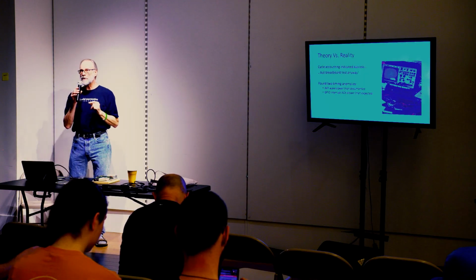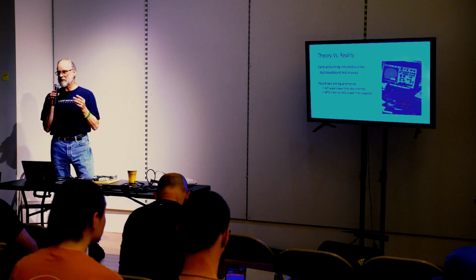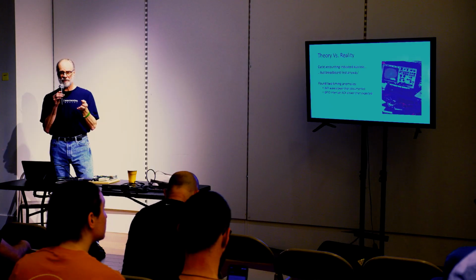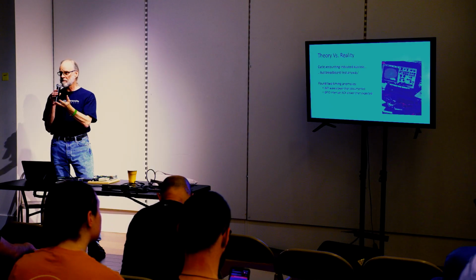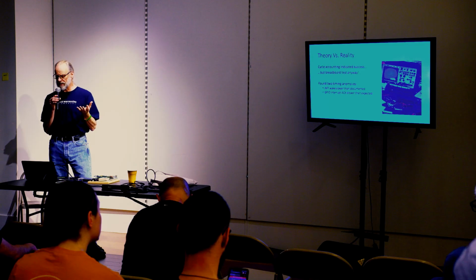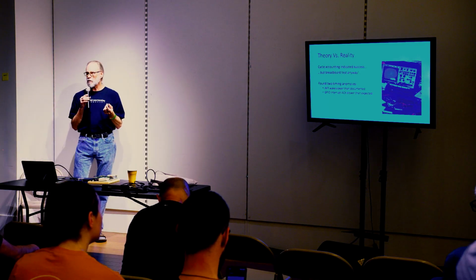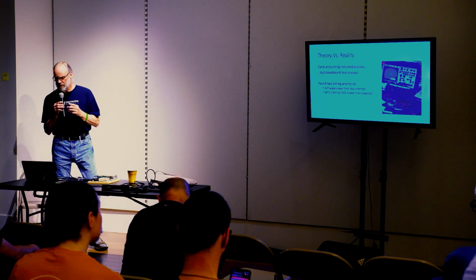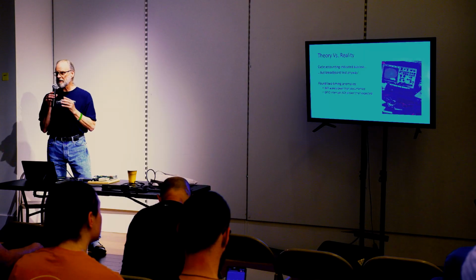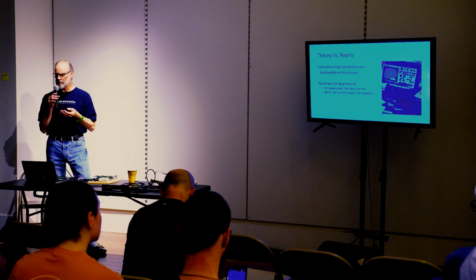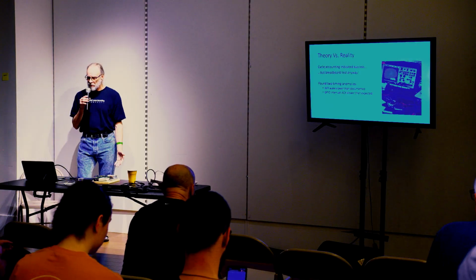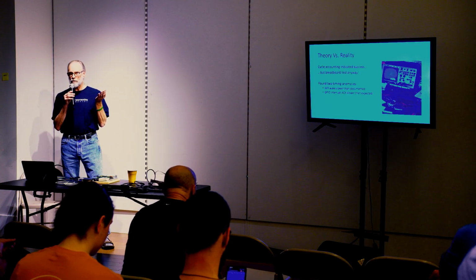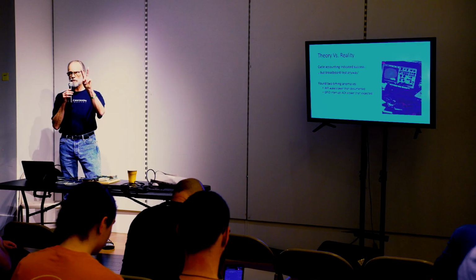And we now get to theory and reality. So I had written the code, and in theory, it should have worked because all my accounting showed that everything should be fine. But it's always wise to test, and so I did, and so I breadboarded it, and I instantly found timing anomalies. So the WFI instruction, in those 1,500 pages of documents, they said it will take 2 cycles.